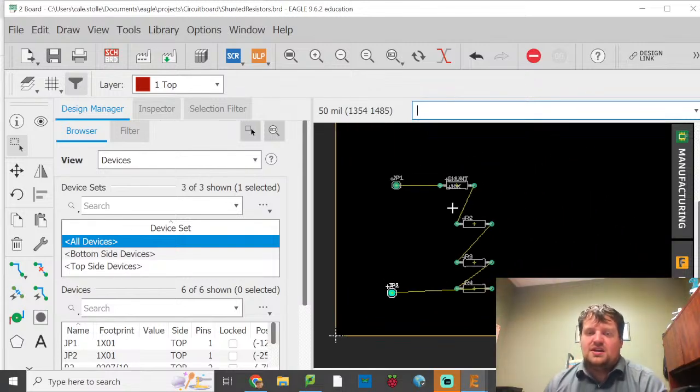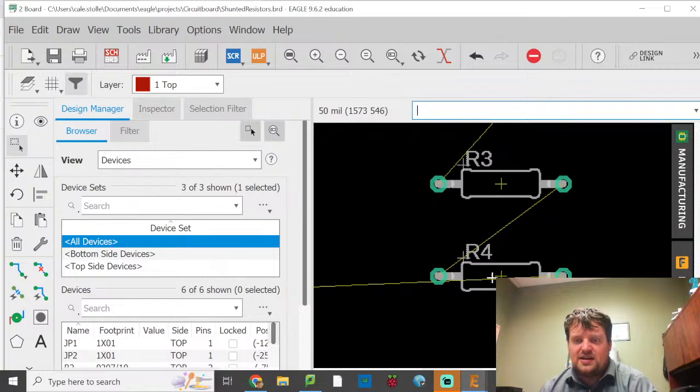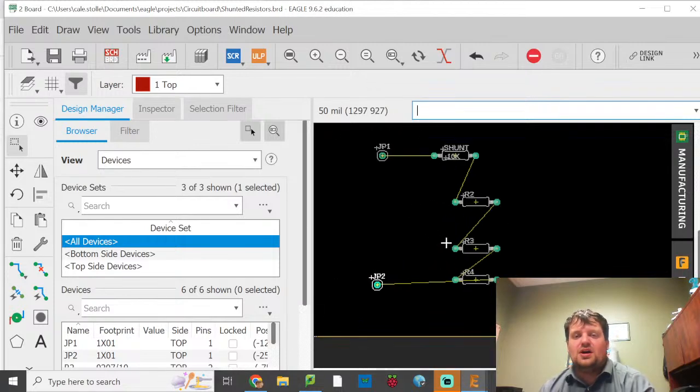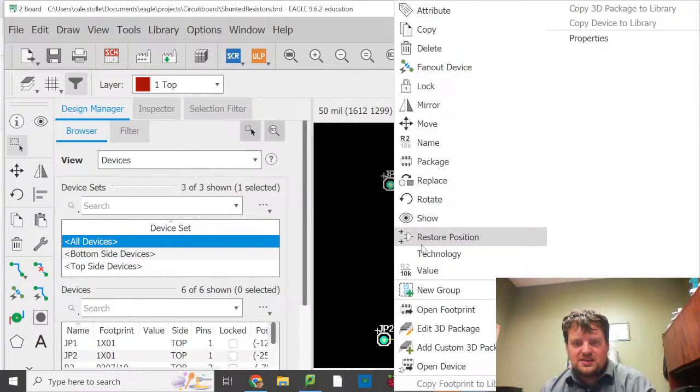So, as an example, if I look at this drawing, this yellow line, as it goes right now, currently crosses this green line. What that means is that I basically am shorting the wire between here and here, the way that this is currently drawn. So I am going to right-click on some of these and rotate them.